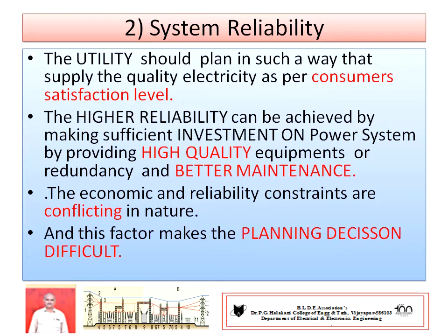When the boiler temperature reaches 60 degrees, the first alarm, the first buzzer, is given. Then electrical engineers should take action to overcome the problem. It shows in the SCADA system. If the first alarm is not attended, after some seconds, the second alarm is buzzed.